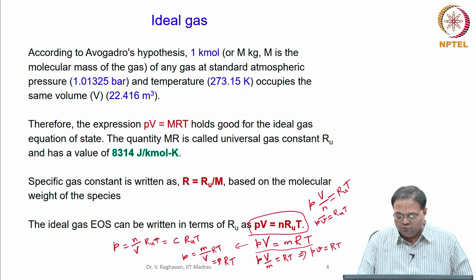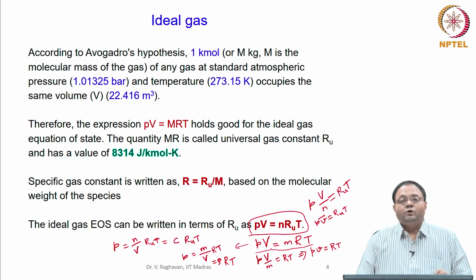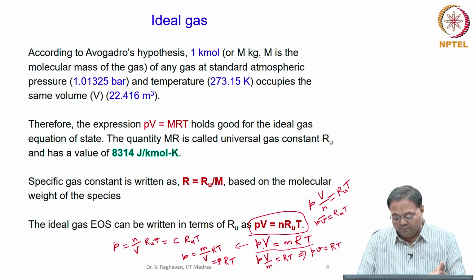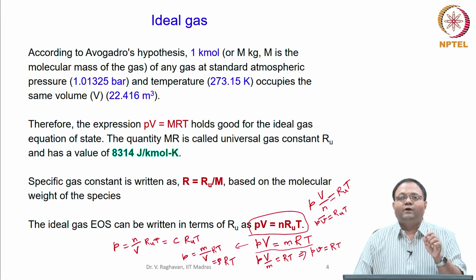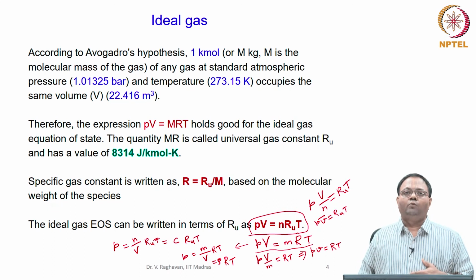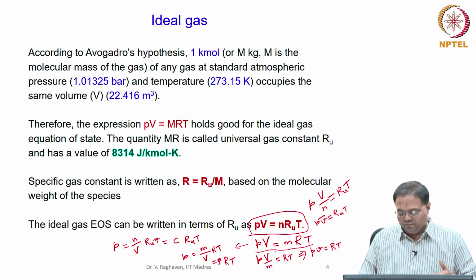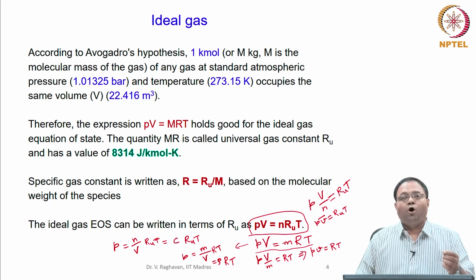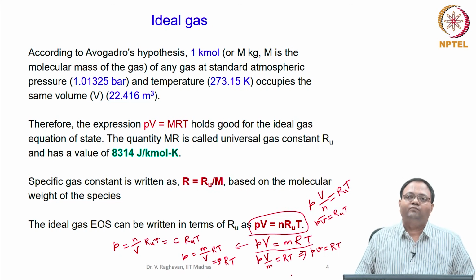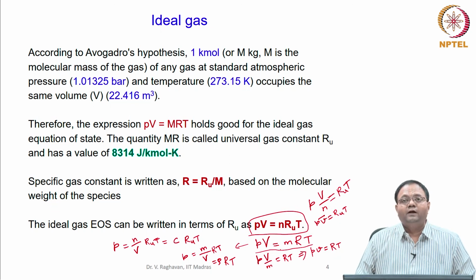If you get mass fractions, at least I know what I will do. I can write this equation and take a volume in which, for example, I take only one component, and the mass of the component is measured to be M1. I will see how much volume it occupies, how much pressure it exerts and so on for a given temperature, and I will get some equation for that. So basically the mass fractions are directly obtained, which is easy for us, and all our other properties I will try to correlate in terms of mass fraction itself. That is the important advantage of gravimetric analysis.